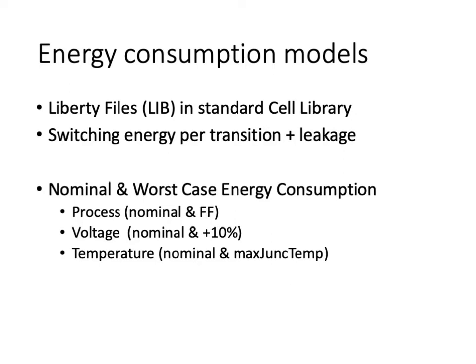But the switching power, the dynamic power that is due to the actual computation, is not enough to estimate the total consumption of a digital VLSI IC. In fact, the equation with the total capacitance only refers to the switching activity associated with charging the output capacitance.